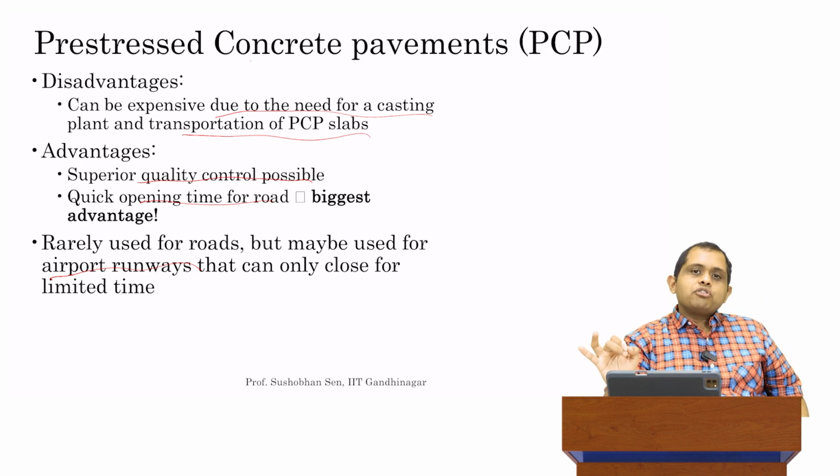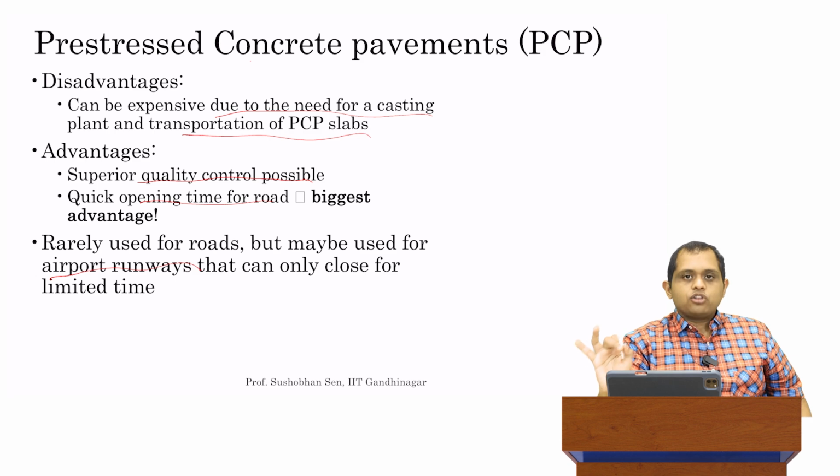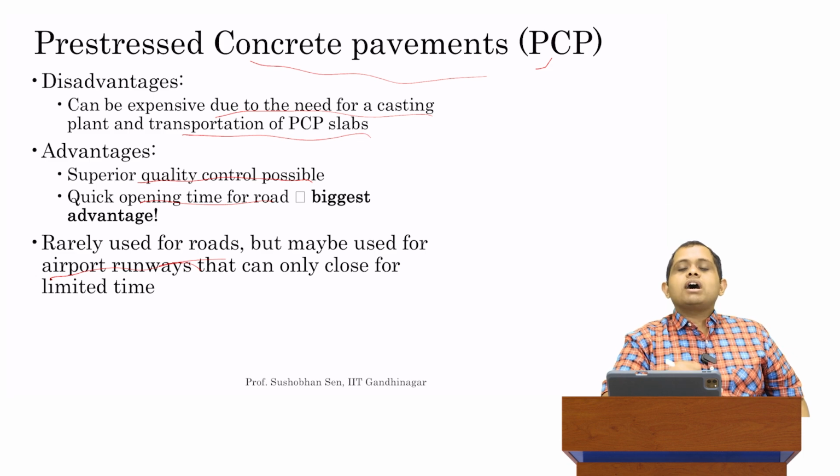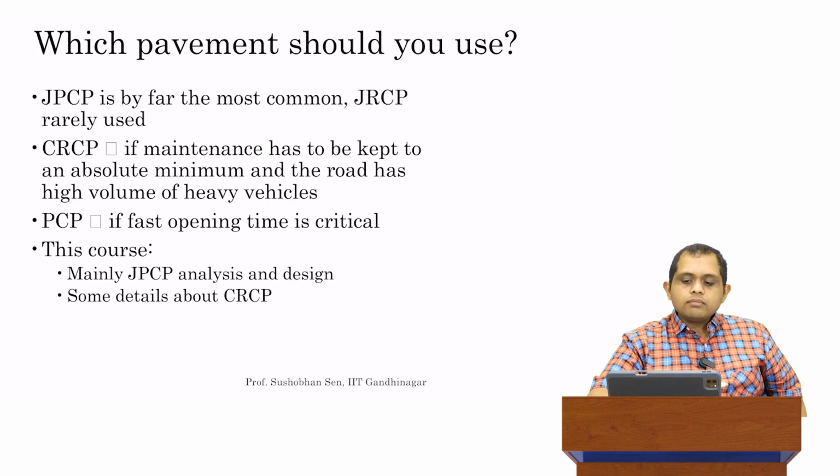In that process, needing to close it for 28 to 90 days to allow concrete to cure is basically a dead end. It's not going to happen. So PCPs are very, very attractive for airport runways because you can shut them for a couple of hours, lay these precast blocks and immediately open it up. They have full strength and they have superior performance.